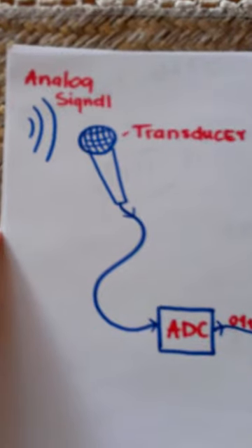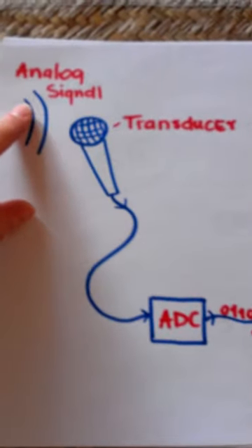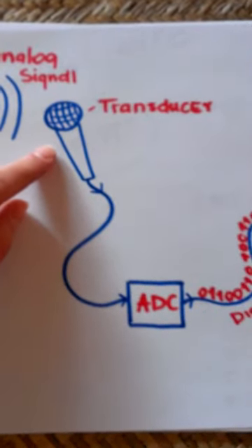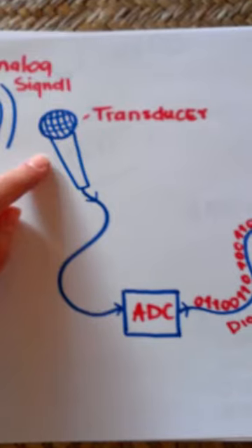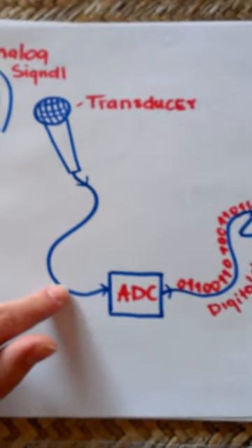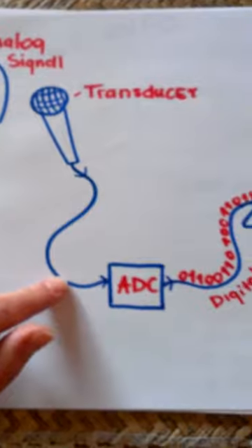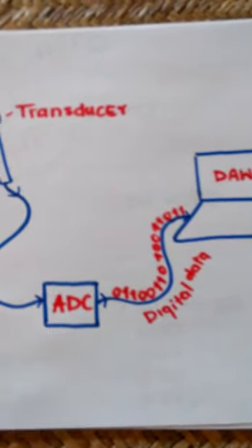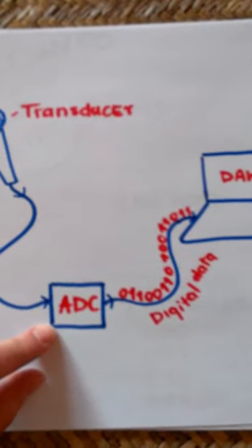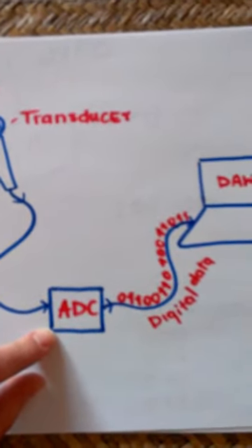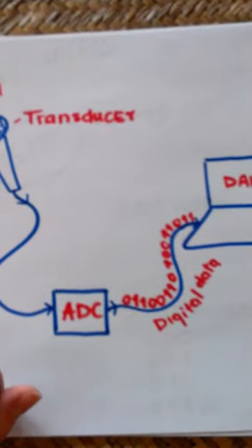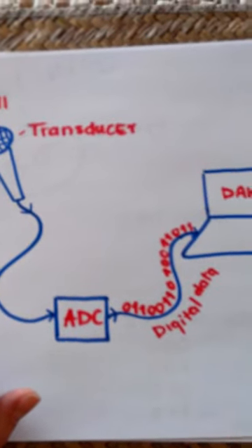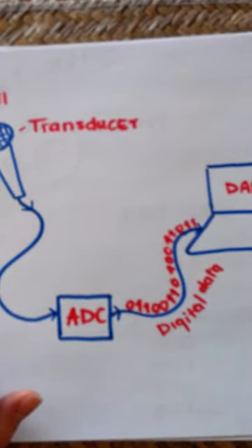as you can see, sound, which is pressure variation in the air, hits an input transducer, in this case the microphone, and by the XLR cable comes to audio interface, where it achieves line level signal. Here it goes through the analog to digital converter, and it's important because the computer can't understand the analog information, so we need some conversion to numbers, and it's binary information.